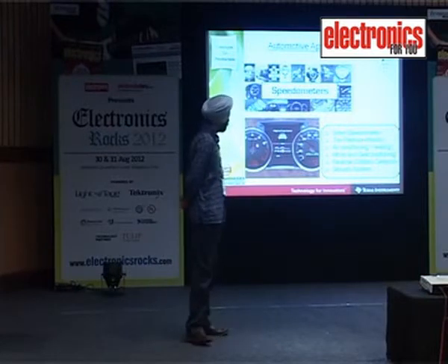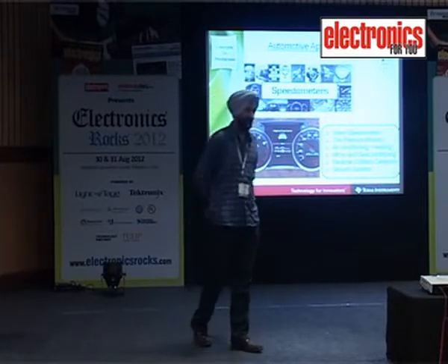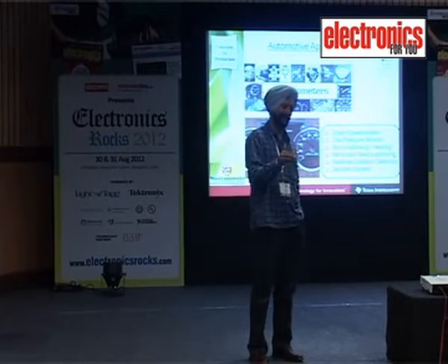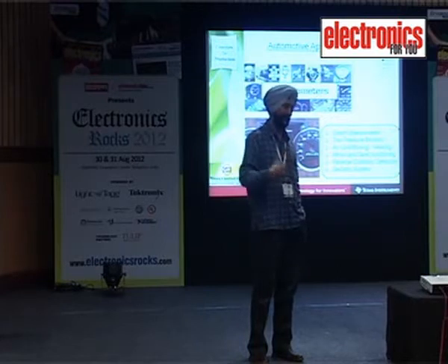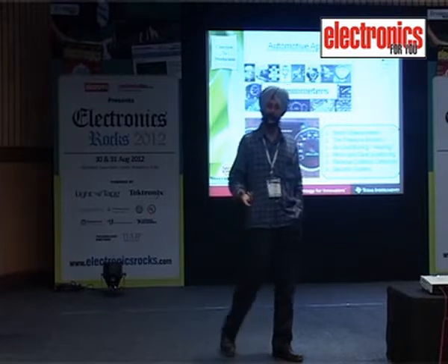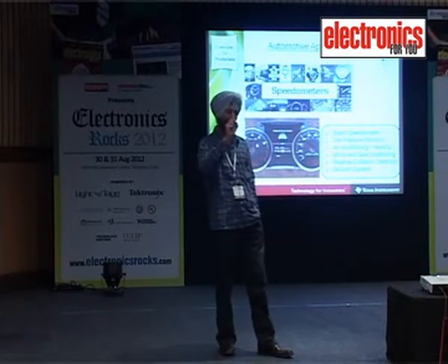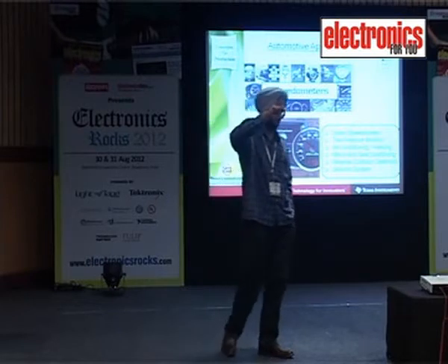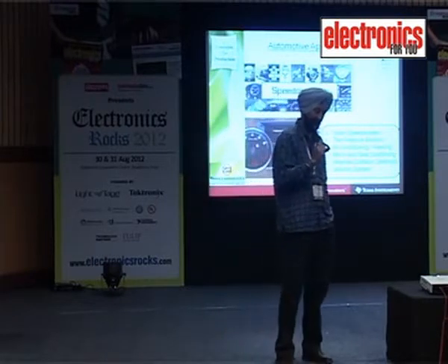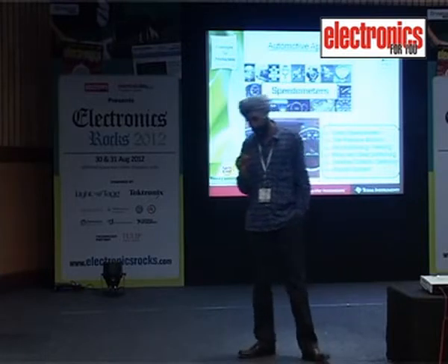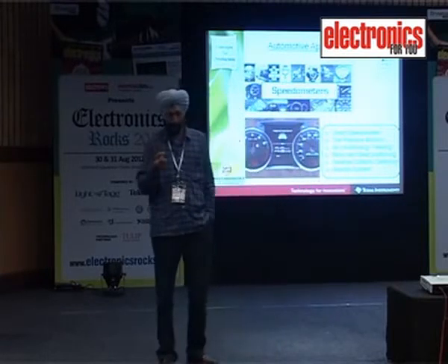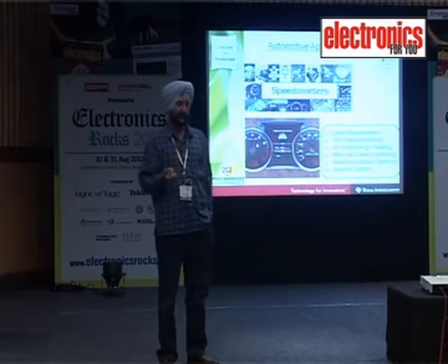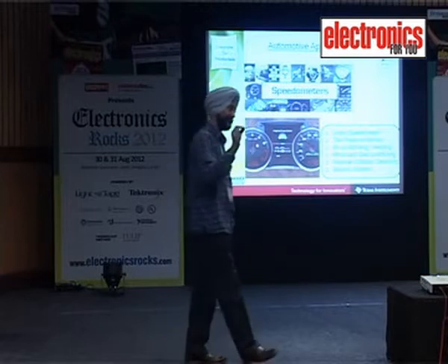See, especially the tire pressure monitor, it's very interesting. Tire is something which is moving. Now you can't have some instrument with wires while the wheels are running. So you can't take any measurement from the 4 wheels. So you have to have something very small in size. Maybe you will have some small cap kind of thing. If you put this cap, that cap will have a pressure sensor. After the pressure sensor, you will have a chip which does the instrumentation, measurement part. Then you will have a radio block. All these things can be achieved in a single chip.